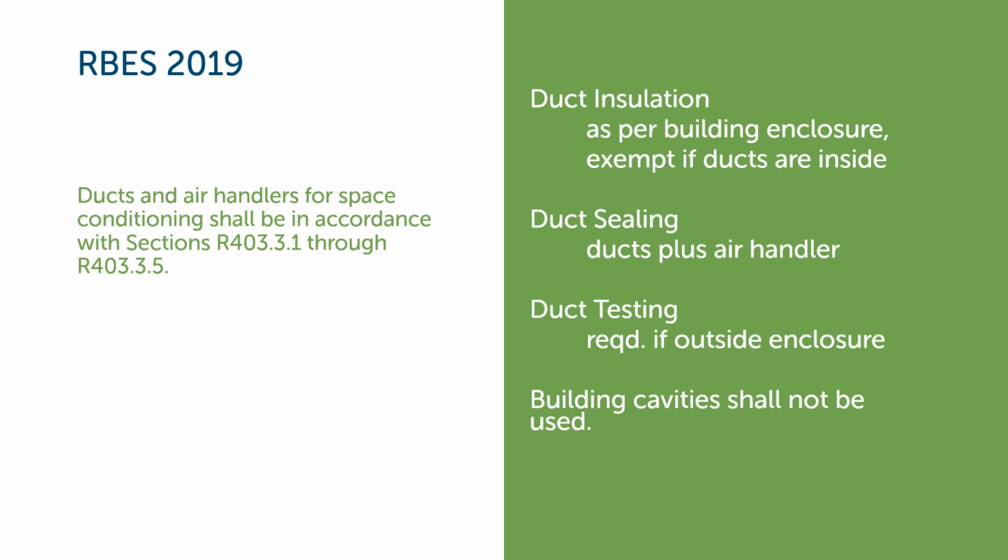And the building cavities shall not be used. So this is new. I think it used to allow building cavities for return ducts, but now that is completely out. Now remember, these code requirements are based on sound science and the principles of all the Manual D stuff we learned in this workshop, and it's not an unnecessary regulation, it's common sense.